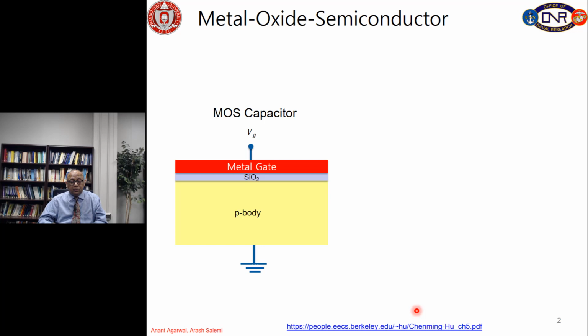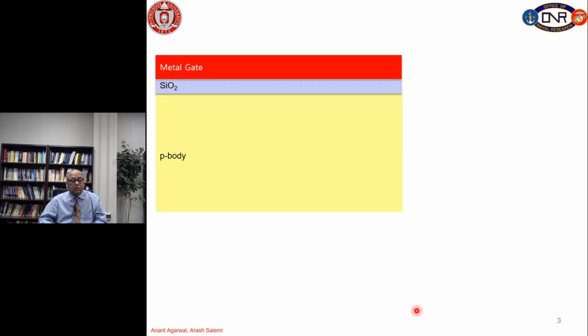All right, so let's concentrate on the MOS capacitor. As we said, it's called MOS capacitor because of metal oxide semiconductor. This is also called the gate oxide or gate dielectric, which generally, as this picture shows, this is a high resolution TEM. You can see this is a semiconductor, this is the oxide, which is amorphous, and then this is the polysilicon, or this could also be metal.